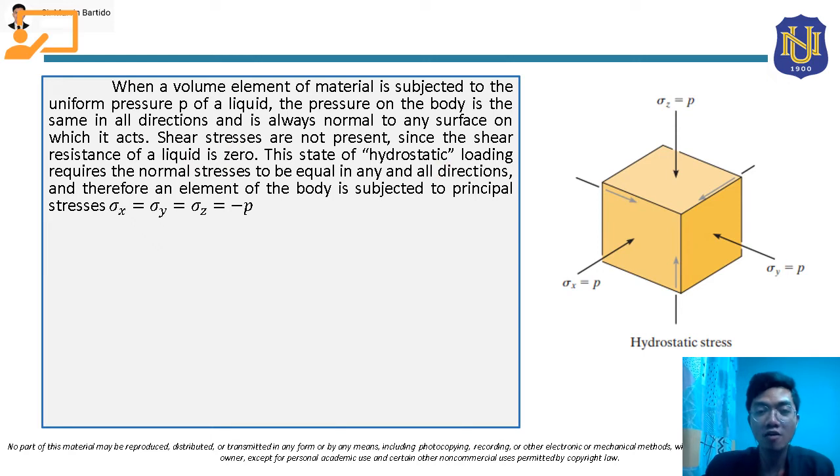This state of hydrostatic loading requires the normal stresses to be equal in any and all directions, and therefore an element of the body is subjected to principal stresses. The principal stresses, sigma x, sigma y, and sigma z, are all compressive stresses.